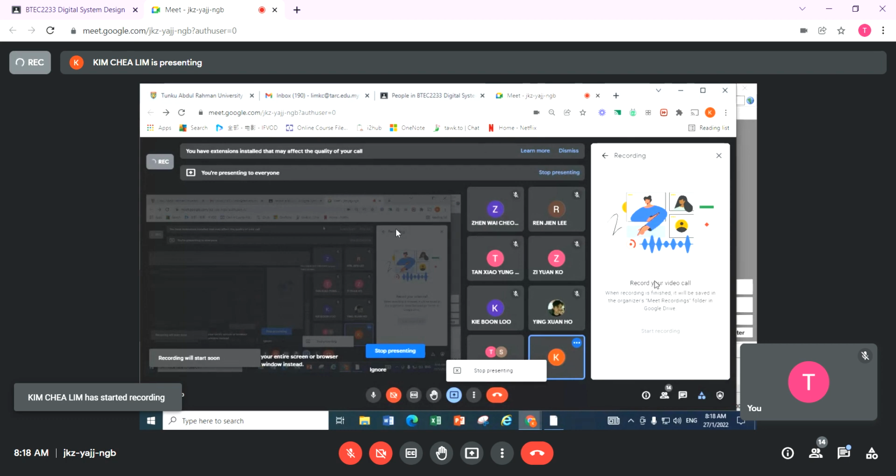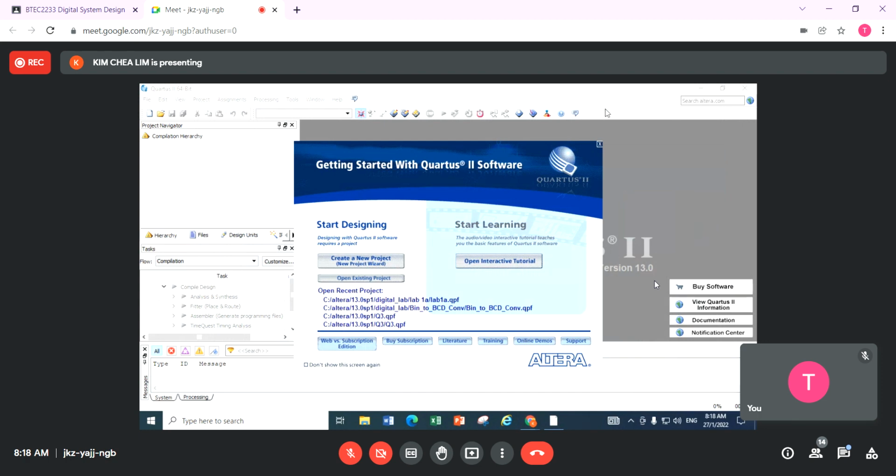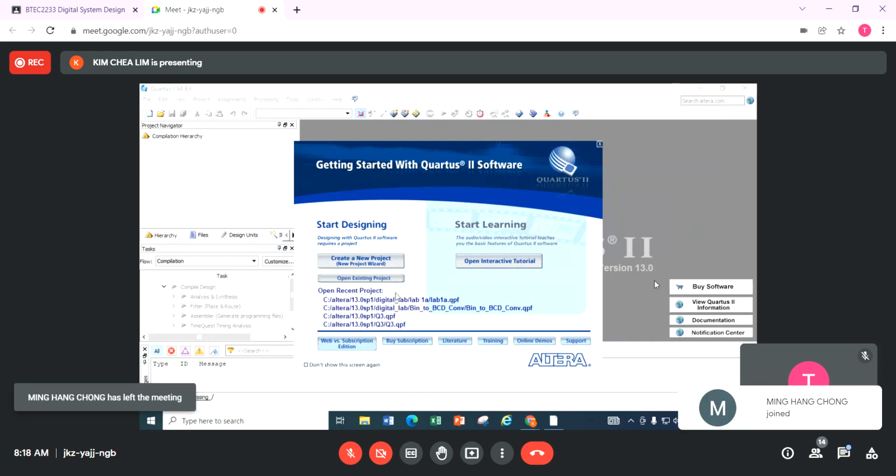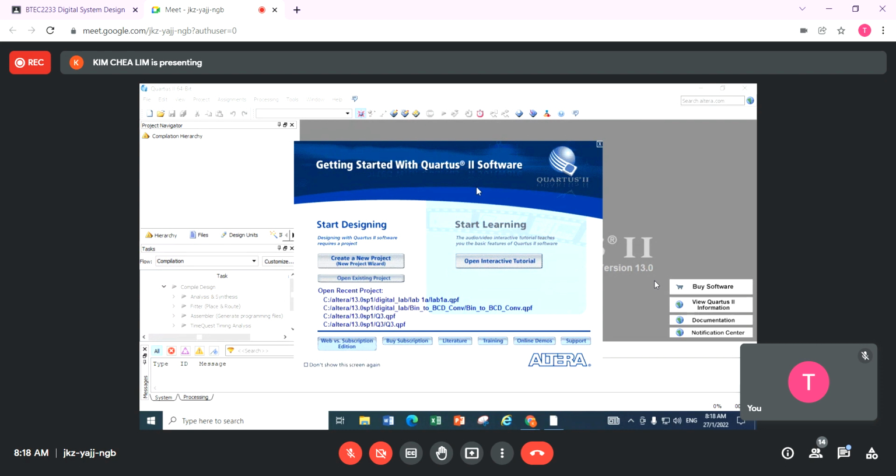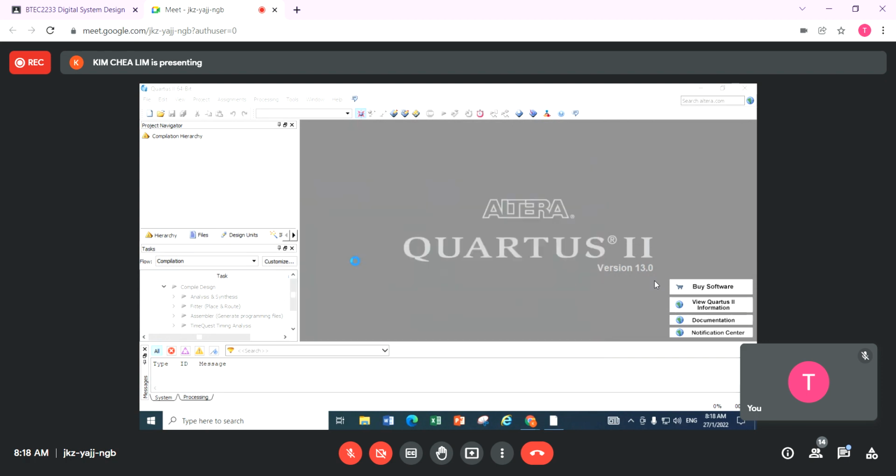Okay, this is presenting already. As I said just now, I go to open up my Quartus II, version 13. So I will see this screen here. Of course, if you are new to this Quartus II, you create a new project. You start off with create a new project.